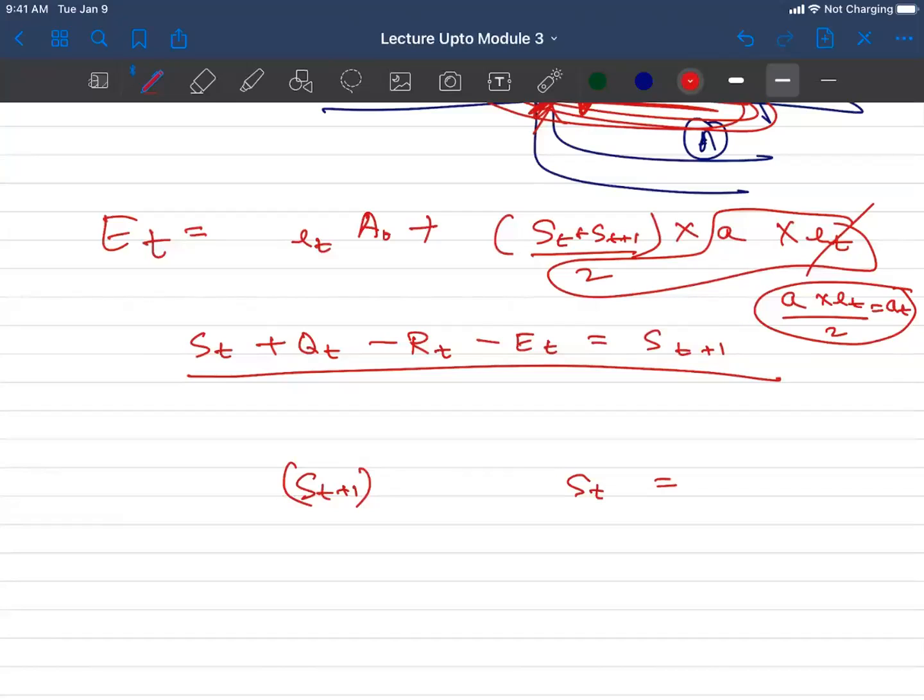Sir, just a small question. Sometimes on the internet I saw that they put a large number of black balls on the water, so the evaporation will be very less. So I think, have we counted that while making the graph of storage versus area? No, we have not counted for that because that is a very costly practice and it is generally not followed in India.